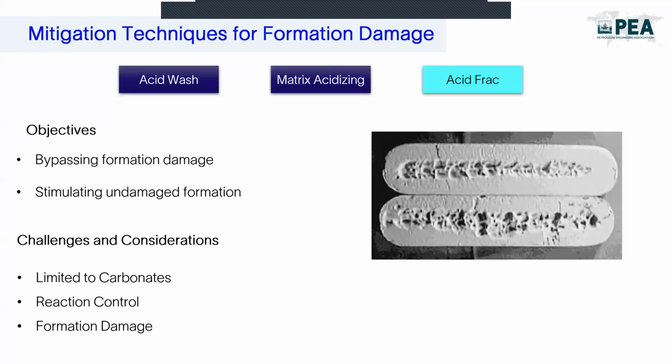In hydraulic fracturing, conductivity is maintained by propping an open fracture created with a solid material such as sand or certain lighter materials. So when we use hydraulic fracturing, these materials are referred to as proppant. We use proppant in hydraulic fracturing. But in fracture acidizing, acid is injected into the fracture created by a viscous fluid, and this viscous fluid is used to create the fracture by injecting it at very high pressure.